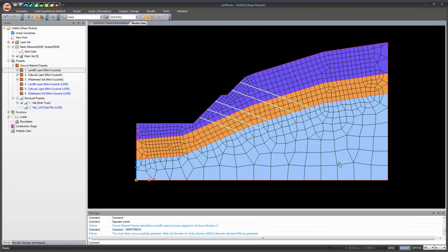Now after meshing, the next step is the boundary definition. You know that boundary definition with 2D models is very easy. But many times what happens, we need to regularly change the model, let's say the mesh size or the properties. So each time we change something in the model, we need to change the boundary condition.